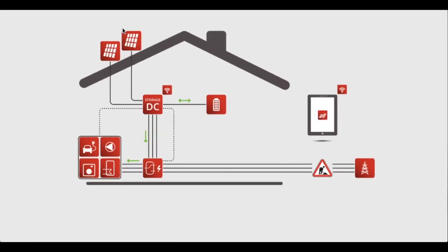I have 14 panels installed to one pole and connected to Storage DC 6 three-phase inverter. The RCT battery 5.7 is connected to Storage DC device. Inverter is connected to RCT power switch. Power switch is connected to the grid and to the house.